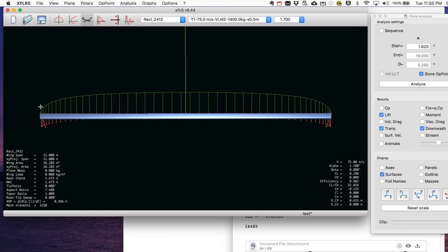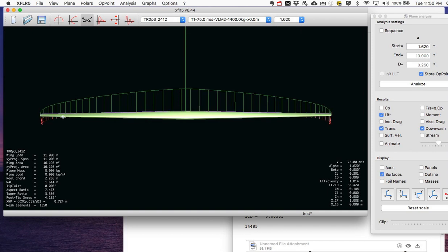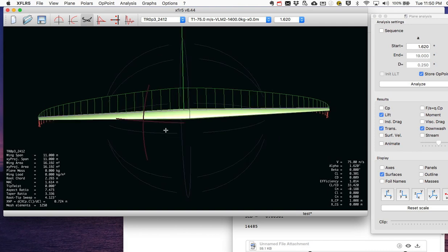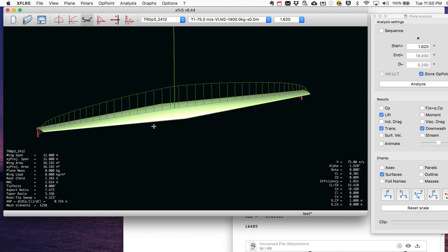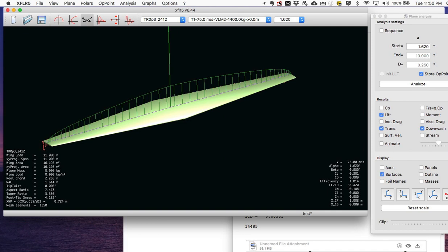You get a lot of force out here pulling up, and it creates this bending moment here. When I go back to this particular case, I have less force out here. The more the force is near to the root. So for the same amount of total lift, I'm getting a smaller bending moment, which means I can increase the aspect ratio of this wing and stay within the limits of the bending moment, and a higher aspect ratio will benefit the induced drag. So this gives a hint that maybe taper is good if you're dealing with these bending moment constraints in particular.